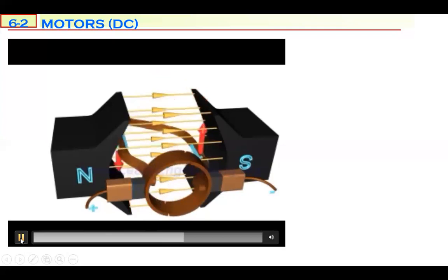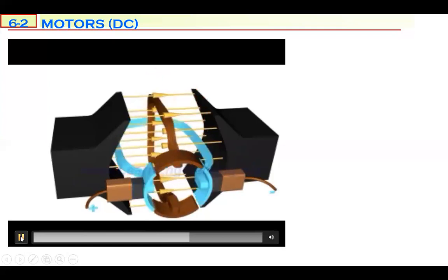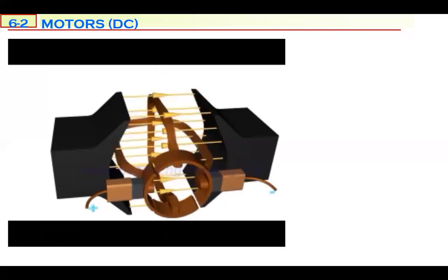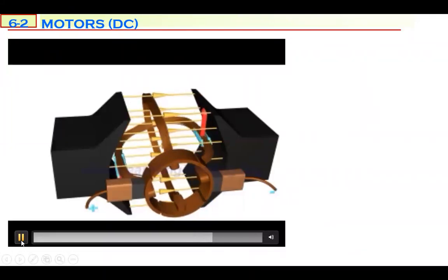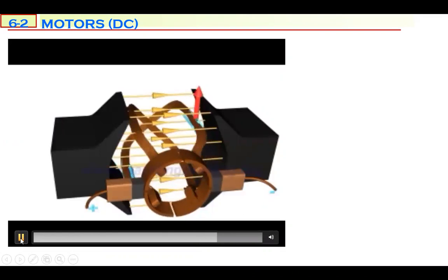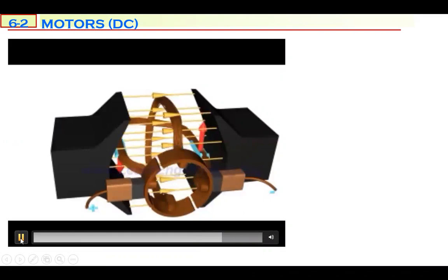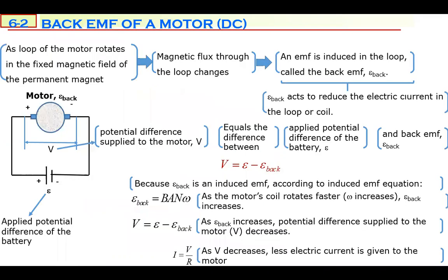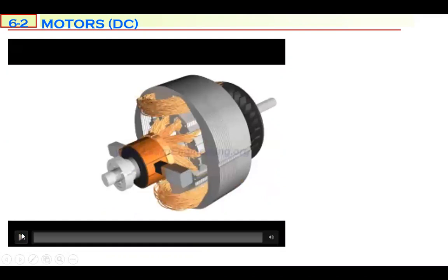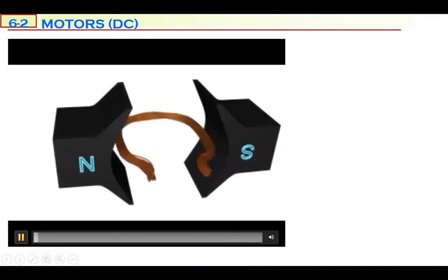To provide a regular rotation, you have to provide one more loop. In this case, rotation becomes regular. In this arrangement, when the first loop is in the vertical position, the second loop will be connected to the power source. So a motive force is always present in the system. So this is much more regular rotation than a single loop. Moreover, the more such loops, the better. Normally, this is the structure of a motor. There are many coils located like this, and they make the rotation much better.